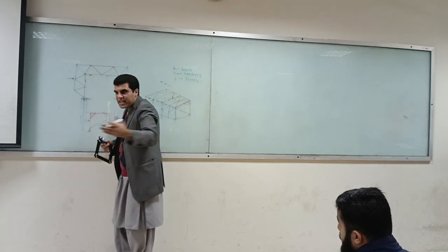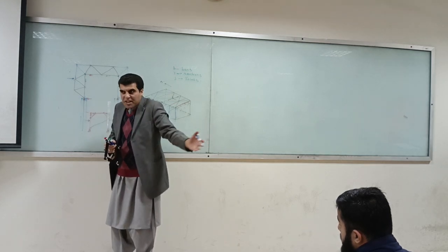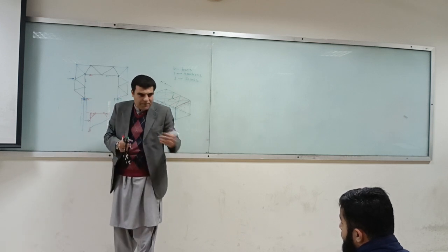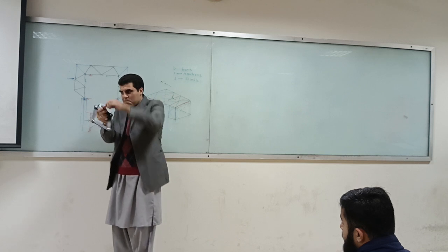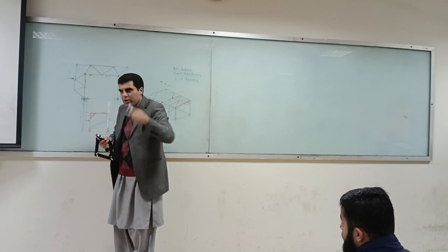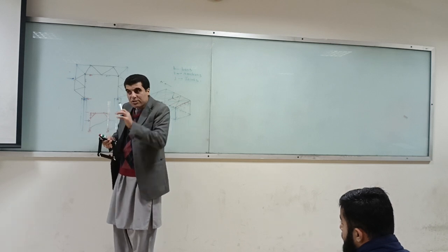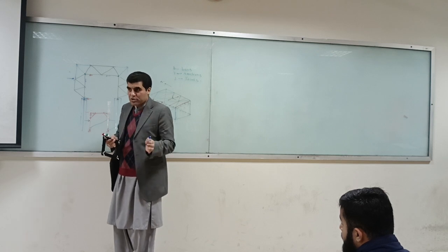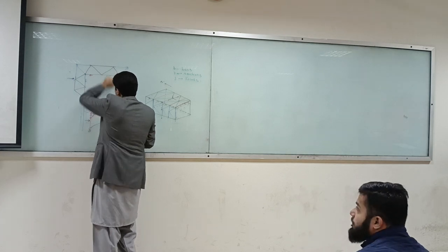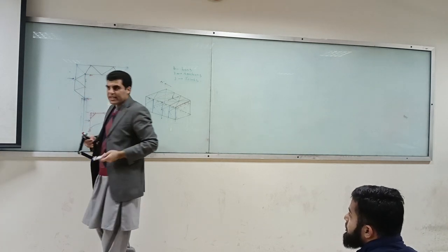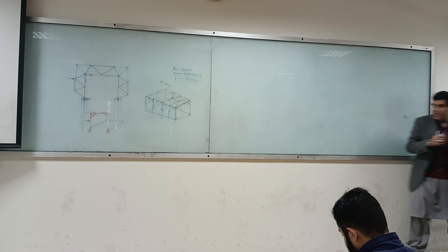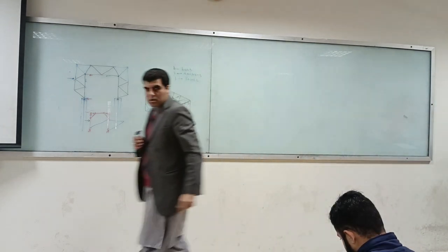But if I provide an ordinary footing, an ordinary foundation like a wall foundation, that is normally a pin foundation. Why? Because this is like a pad, and a pad can always rotate. It can't take the moment. So you have to make your judgment whether it is a pin or a fix. Those supports are external supports. And whatever is inside, in between these two supports, these are all internal hinges. Okay? Is it okay? Yes.